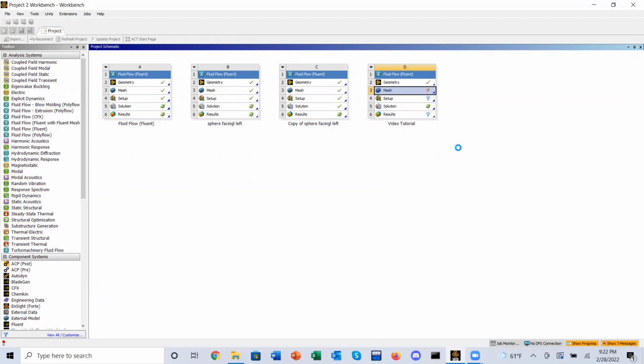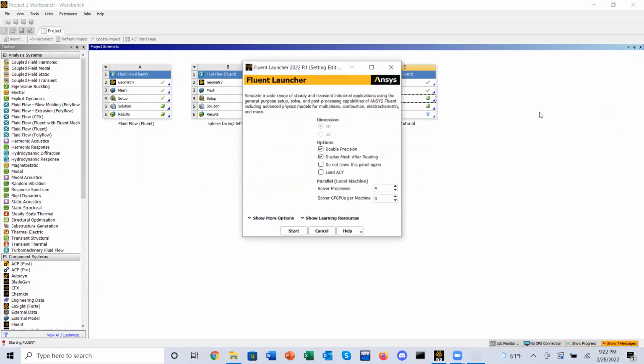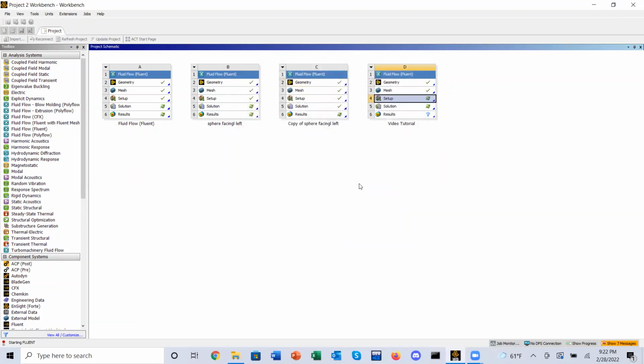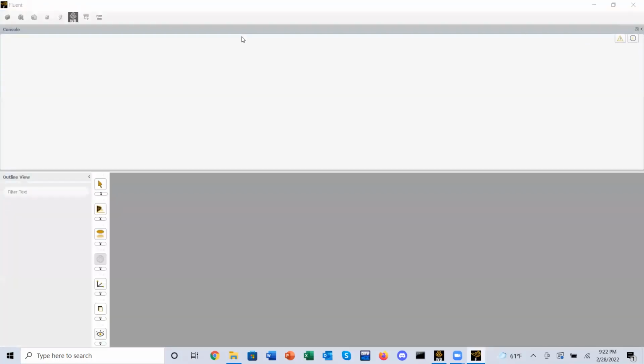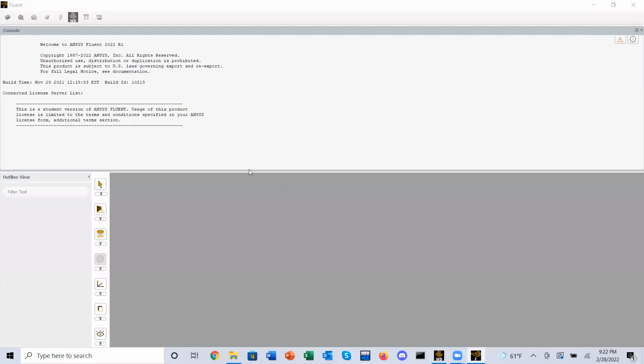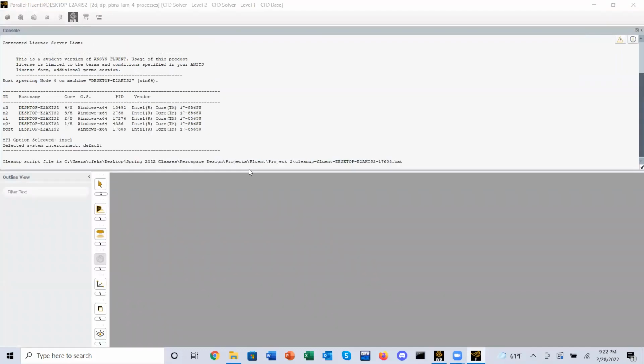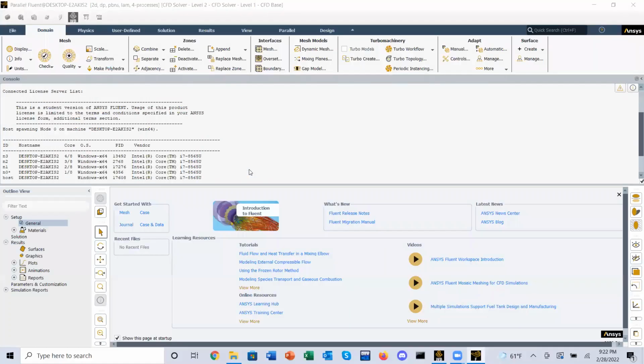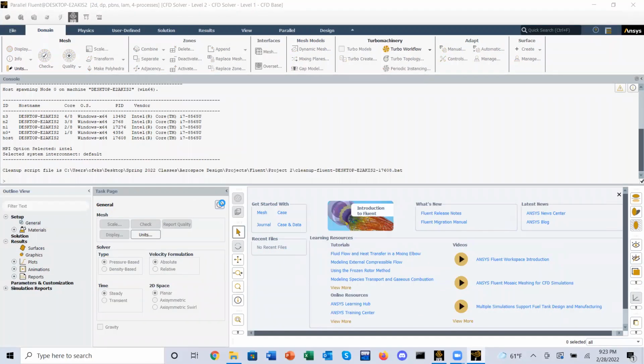As soon as it's done, we can go to setup, and this project is pretty short compared to the last one, I would say. In setup, everything has changed, so we do want it to change. We're gonna go on my computer, I'm gonna go double precision, and then I think I have 4 solid processes. What's it called? Cores? Something like that. This is it. All right. And then I think there's only like 3 things we have to do in this section, so it should be done very shortly.